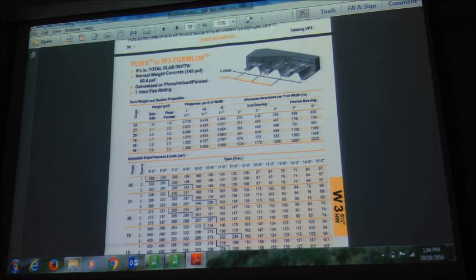That 3-inch deck means the deck from bottom part to top part is 3 inch, and then on top of that we have another 3.5 inch of concrete. Its weight is 60.4 pounds per square feet, and depending on how thick a metal deck you want to use, we are going to use this one. That's a very common commercial deck.